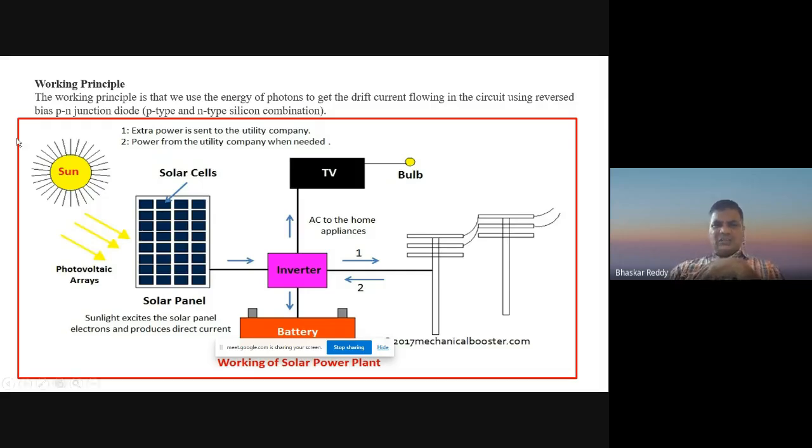That's why the solar panel, during cloudy situations and during the night, is acting as an open circuit. When the intensity of the light is maximum, then it is acting as a short circuit. That's what they indicate as the open circuit voltage and short circuit current. Every panel will indicate an open circuit voltage and a short circuit current.